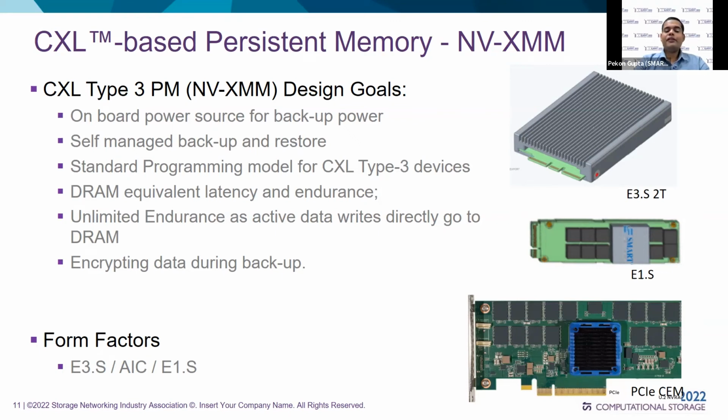The second important aspect is that it should be self-managed. Unlike NVDIMM-N, there is no host interface which can trigger a backup operation. There can be in-band signaling where the host indicates that power will be lost, but in an abrupt power or unmanaged power fault, the power fault has to be detected locally by the module. And therefore, it's important to have a circuit on the module itself which can detect brownout conditions, power loss conditions, and power restore conditions.